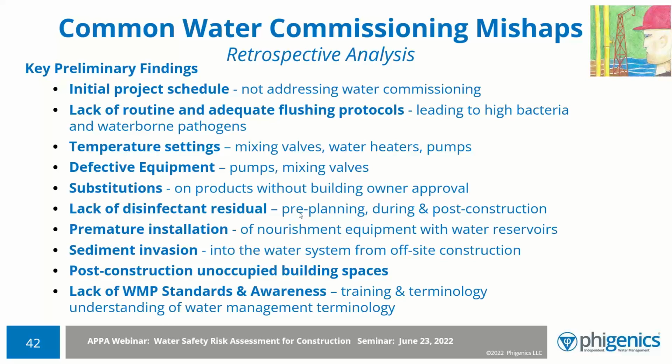Disinfectant residual. Did anyone plan for this during the construction project or not? Did you prematurely install nourishment, ice machines, other water reservoir equipment that you shouldn't have, and do that closer to opening day? Do you have sediment and soil invasion either on your site from civil activities, which is very common in these community settings, or do you have your municipality doing off-site construction? Are you planning to occupy the building right away? Some people build and occupy parts of buildings and they don't occupy the building completely, and you maybe have to valve off, or maybe you shouldn't fill parts of the building rather than having the water sit there.